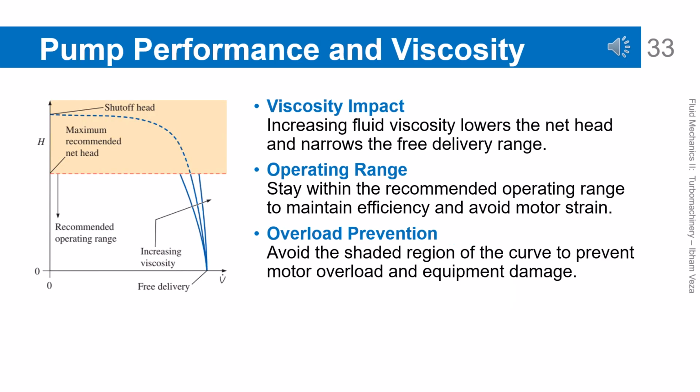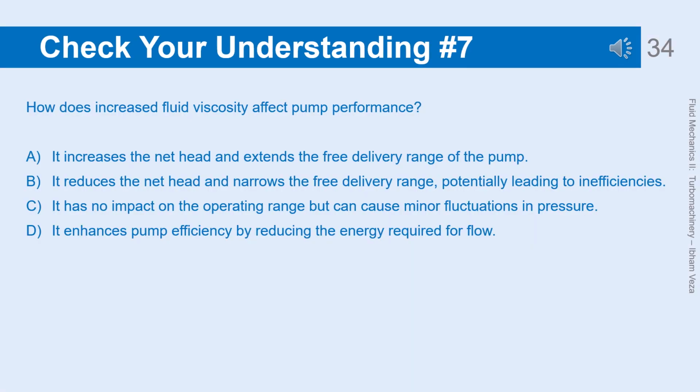Pump performance and viscosity. An increase in fluid viscosity causes a reduction in net head and narrows the free delivery range. This means the pump works harder and the motor is more prone to overload. Therefore, the pump must be operated within the range recommended by the manufacturer. The shaded region on the curve indicates conditions that should be avoided. Pump selection must consider the working fluid viscosity. Correct answer, B. It reduces the net head and narrows the free delivery range, potentially leading to inefficiencies.